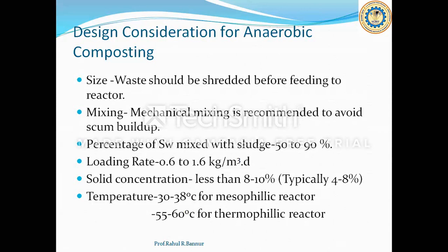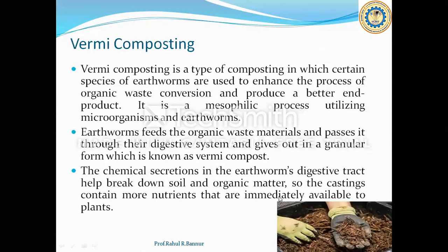Loading rate is 0.6 to 1.5 kg per meter cube per day. Solid concentration is less than 8 to 10%, typically 4 to 8%. Temperature is maintained at 30 to 38 degrees Celsius for a mesophilic reactor and 50 to 60 degrees for a thermophilic reactor. At these temperatures, two types of bacteria play the main role. At 30 to 38 degrees Celsius, mesophilic bacteria play the main role. At 55 to 60 degrees, thermophilic bacteria play the main role.